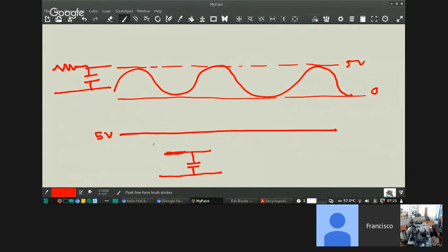Suppose you want a higher resistor, say 1K, and you start drawing 100 milliamperes, so you will have a drop of something like 100 volts. So you won't have 5 volts over the other end. That's why we don't put a resistor in the power line, because there will be a drop. Okay, and this will not draw any current from here. Yeah, in the case of a signal, it won't draw much current, so we can put a resistor over there. In fact, we don't want the signal line to draw power, so we put a current limiting resistor over there.